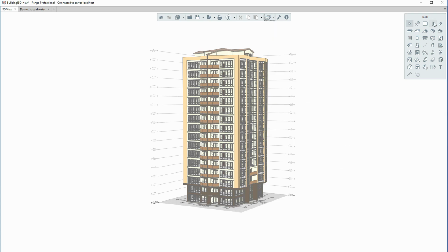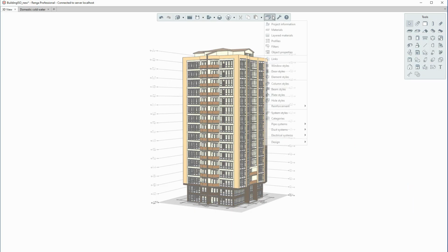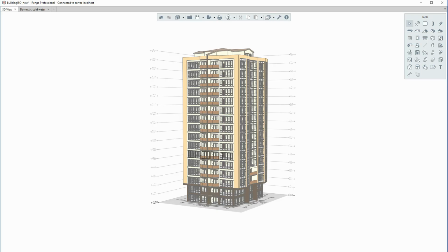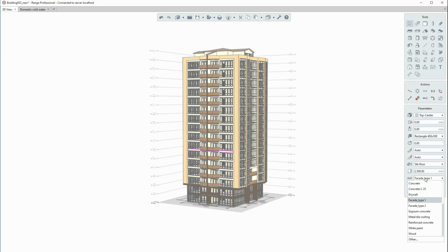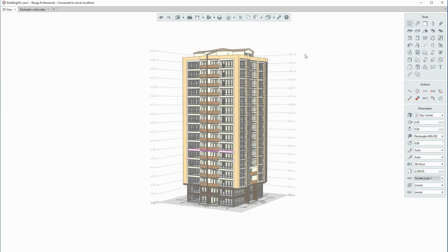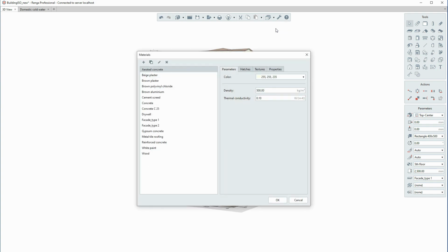Material is assigned either in the material parameter of the mentioned above tools or on the Parameters tab in the Style editor of the object. When selecting a material style, you can create a new material if there is no suitable one in the suggested list. For this purpose, select the other option in the list of materials. To create and edit materials, it is also possible to use the Manage Styles section, subsection Materials on the primary panel.